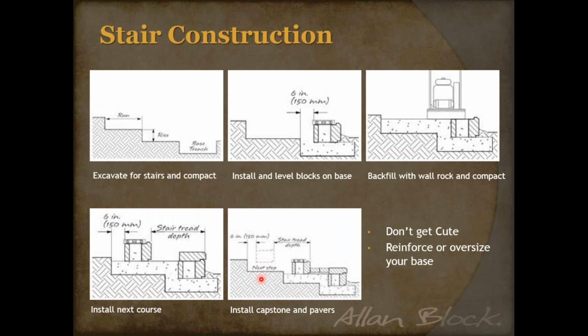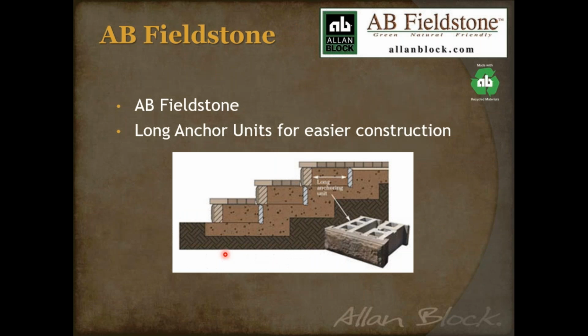And you just go ahead and make sure you repeat those steps as you install the caps and pavers or pour concrete all the way through. But like I said, I like making sure your base is nice and sound. I like making sure that you've got some grit in there. I know guys that will, if I use this bottom picture as an example, dig out this whole area and even bring in block below it to make sure they've got consistent. And that holds true. If you can rest it on additional block, that helps.